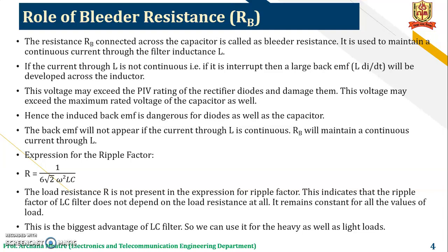This voltage may exceed the maximum rated voltage of the capacitor as well. Hence, the induced back EMF is dangerous for diodes as well as the capacitor. The back EMF will not appear if the current through L is continuous. RB will maintain a continuous current through L.